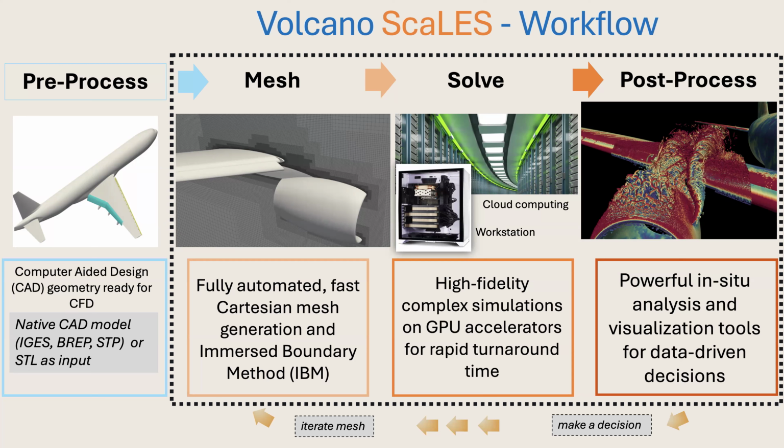For this case, it's 5 millimeter, 4 millimeter, 3.2 millimeter simultaneously, and that's actually a very difficult process with non-isotropic and non-automatic grid generation. But with Cartesian octree, this can be done very easily, and it removes the verification question of whether I am solving my PDEs correctly or not.